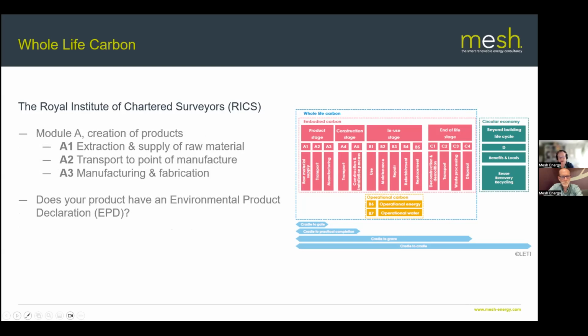And that is a third party assessment as to the global warming potential of the materials and products you're prepared to use for your project. And while this is not so important in, say, domestic projects, unless the clients are particularly aspirational, it is certainly part of the BREEAM structure if you're pursuing credits surrounding material use and reducing your embodied carbon that way.